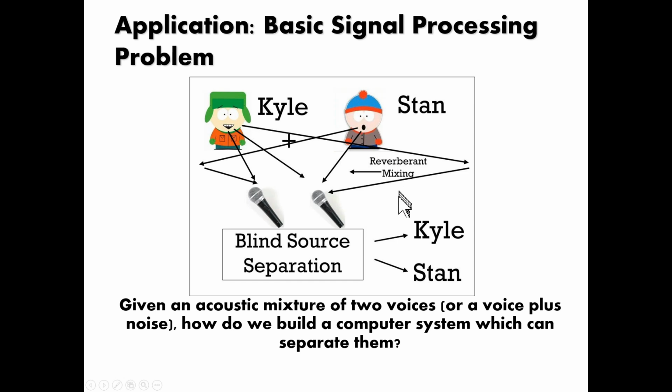It's a sort of very advanced type of filtering, isn't it, really? But you might think, well, why don't we just filter them? But of course, if you filter them with a normal filter, you find that with two voices, the frequencies overlap one another. And so you can't filter them just with an ordinary convolution filter, if you like. So what you need to be able to do is somehow find what these transfer functions are and kind of invert them. But you can't do that because you don't have that information. But the theory goes around that anyway. So clear the applications: hearing aids, mobile phones, speech recognition.